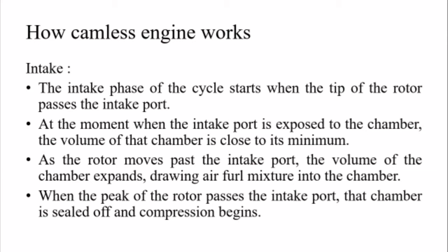The volume of the chamber is close to its minimum. As the rotor moves past the intake port, the volume of the chamber expands, drawing the air-fuel mixture into the chamber. When the peak of the rotor passes the intake port, the chamber is sealed off and the compression stroke begins. After the compression stroke, we know that the combustion stroke takes place.